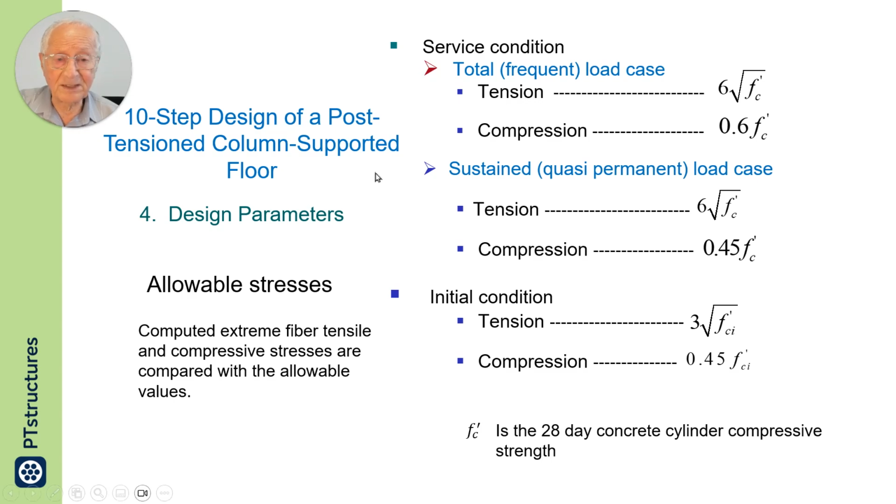Sustained is in ACI left to the judgment of the design engineer that during its lifespan the slab is not going to be loaded to the maximum allowable value. Live load specifically here will be on, off, or often at a lesser magnitude than the maximum. So there can be larger allowable values.